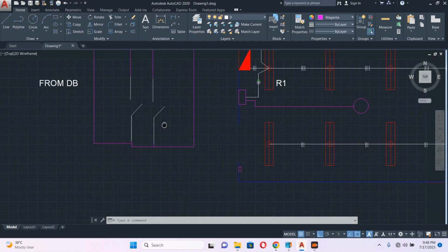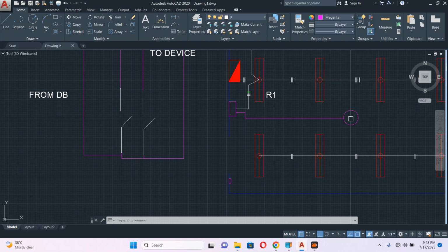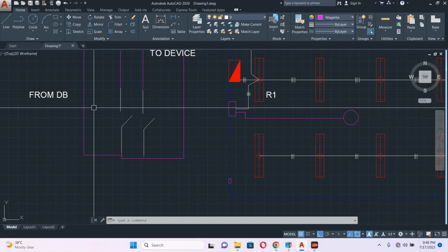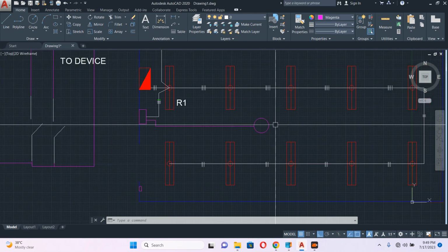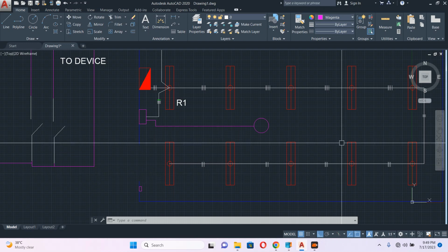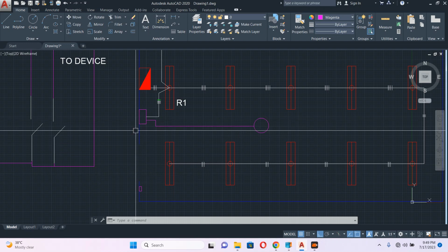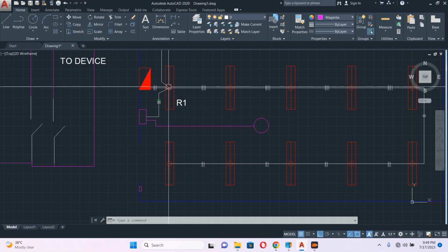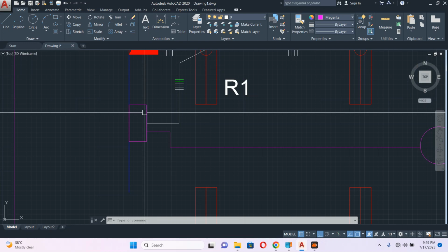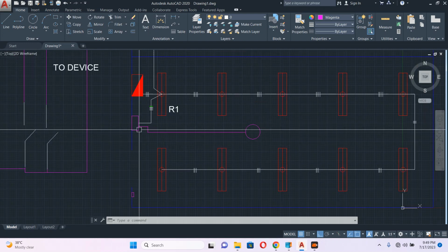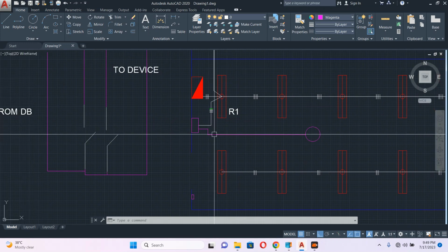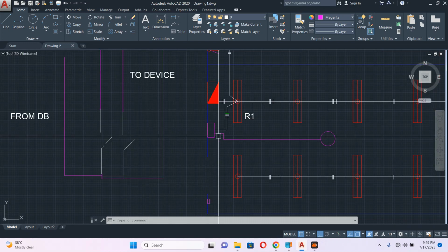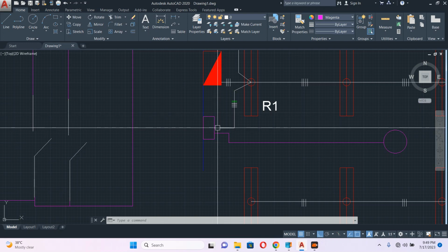Same as something like this. Here we are switching on by our hand. Here the relay will work to switch on. That's the difference, a small difference. So this is a presence sensor. When you come here, this will sense and give the signal to the panel. The panel switches on the light. And here you can program which light has to be on: all, or one, or three. This one has a panel, specialized people, lighting control people. They have a specialized panel, they will program inside.